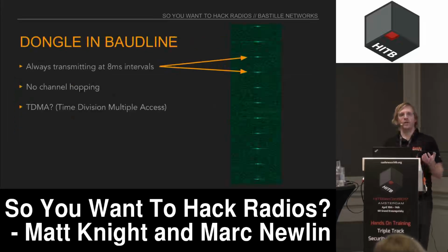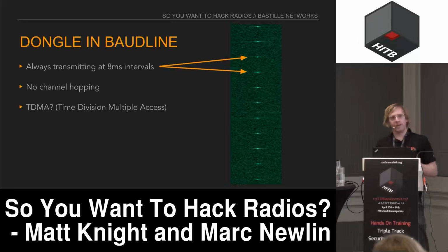So the first thing we want to do is figure out what these devices actually send over the air. Because we have 2 transmitters, the keyboard and the dongle, we can start by plugging in the dongle, pulling up a spectrogram, and trying to see what's happening. It turns out that it actually camps on a single channel, so it's not hopping, and it's only one channel. So the differing channel numbers in the SEC documentation is now irrelevant.